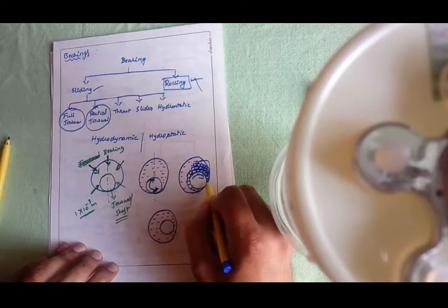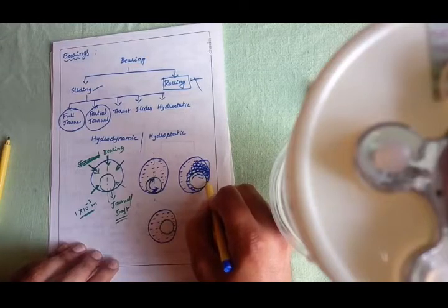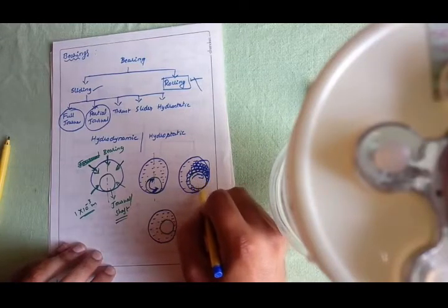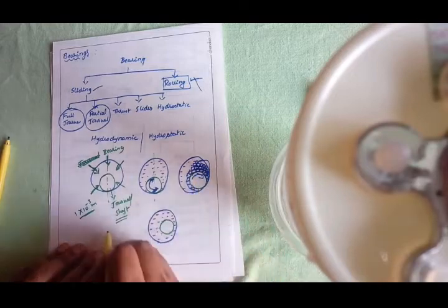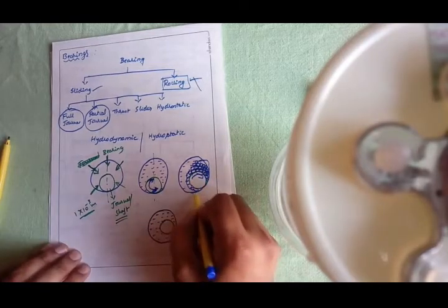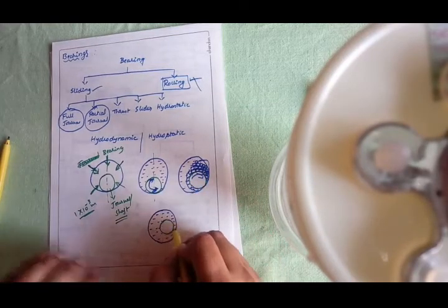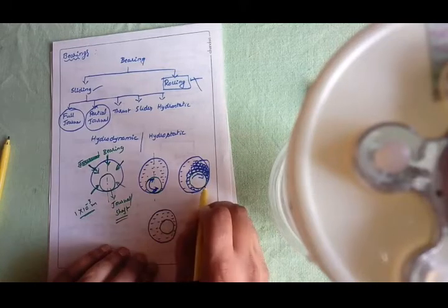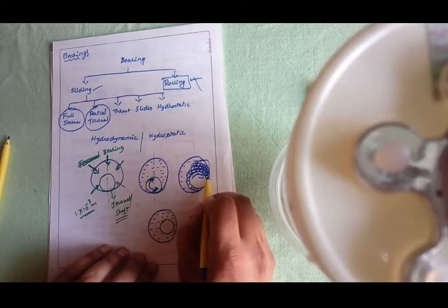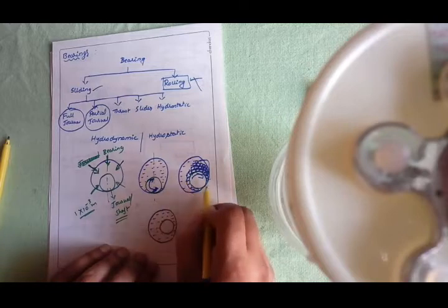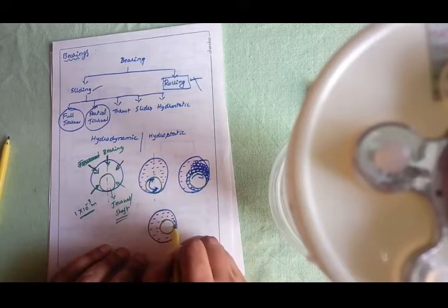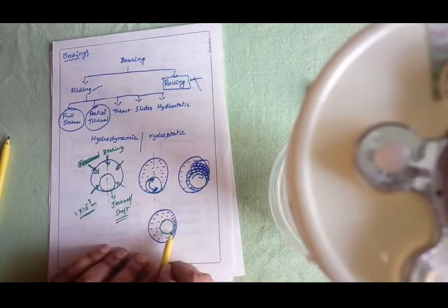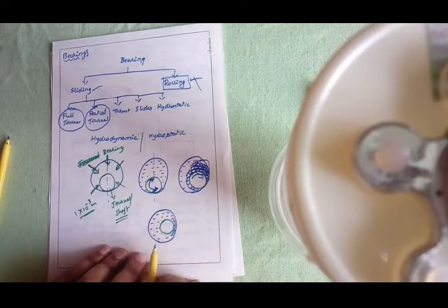Now there is a pressure difference. What is going to happen is, these fluid particles lift the journal and move to the other side, thereby a convergent and divergent section will be formed. Once enough pressure is built at this location, it is automatically going to lift your journal and move it to the other side. Like this, you can see a gap between the journal and the bearing surface can be achieved.